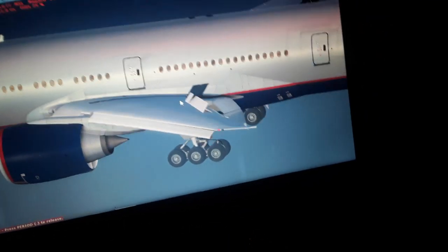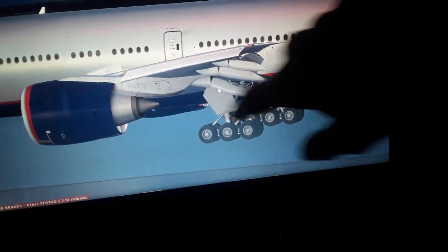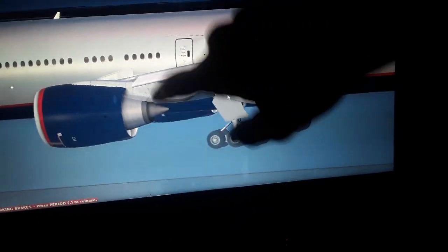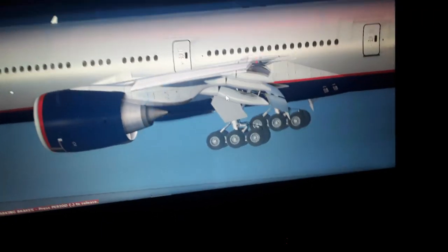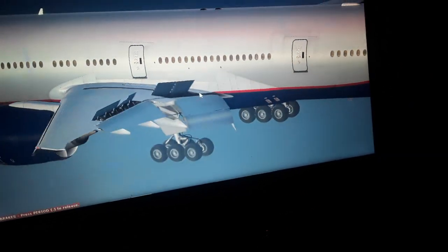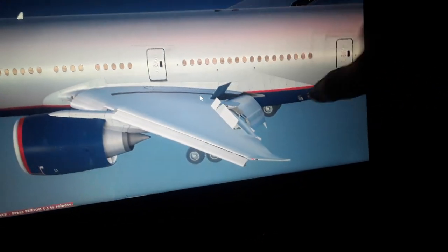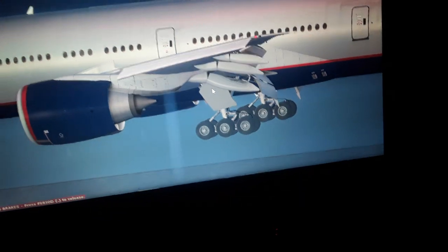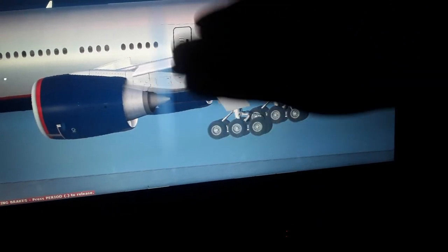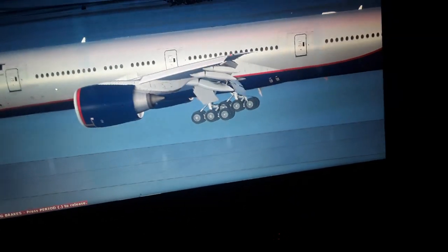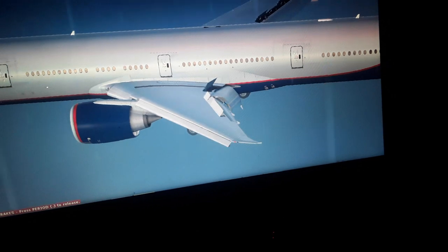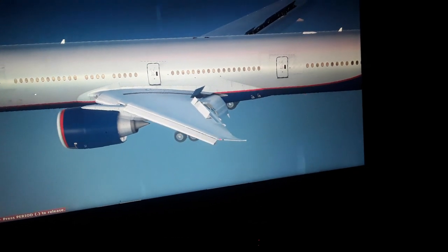You have more curvature on top. On the bottom surface of the wings, the airflow is moving slower, so you have higher air pressure below the wings, while above the wings you have higher curvature, so the airflow is moving with higher airspeed above the wings, so you have lower pressure above the wing. So you have higher pressure and lower airspeed below the wing. So the higher pressure will push the wings up into the air as you move forward, as you accelerate and overcome the stall speed.